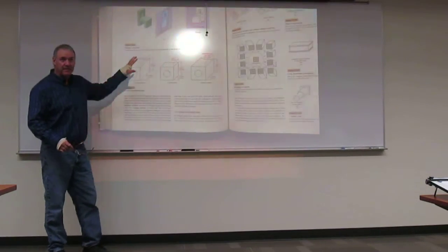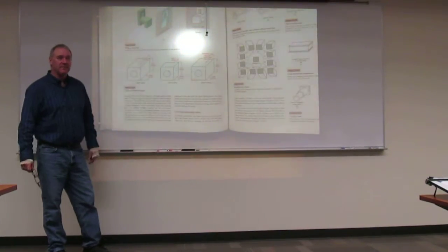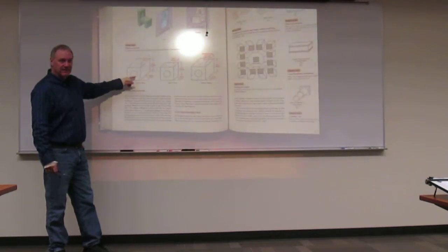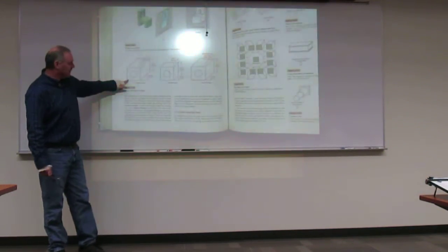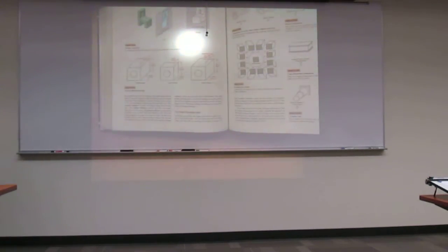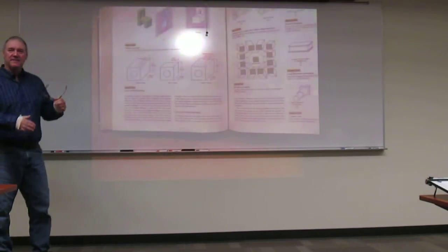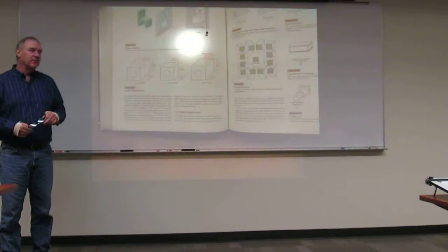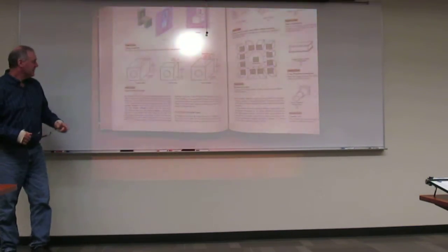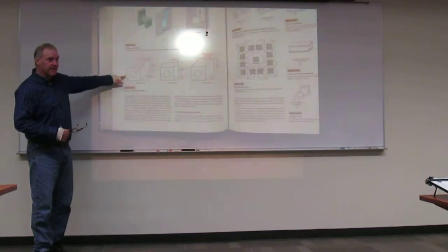It doesn't look the same due to some of the conventions they're pulling, but they are. And again, that's taking care of that front side. Now the cavalier is drawn much like an isometric, in that the receding axis is drawn full scale. You're still going to have lines that aren't parallel to those that are going to create a lot of distortion like a non-isometric line. So the cavalier, this is your main one right here.